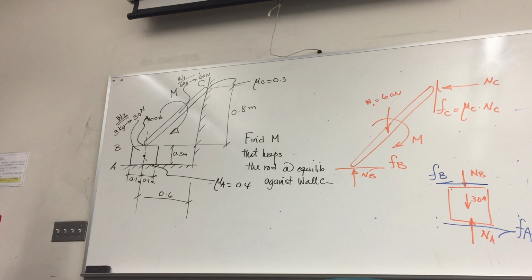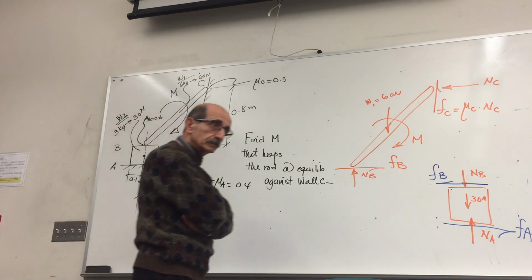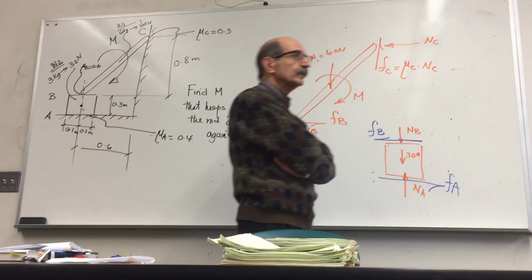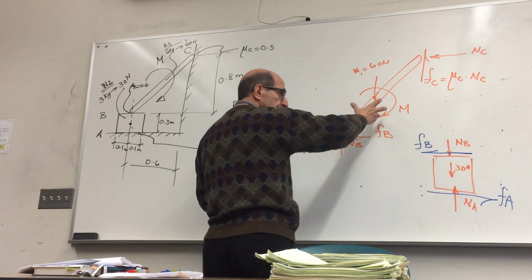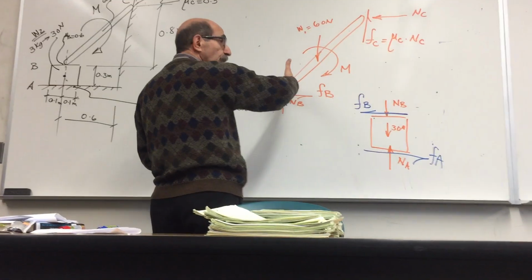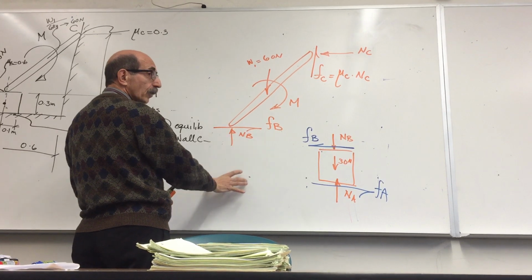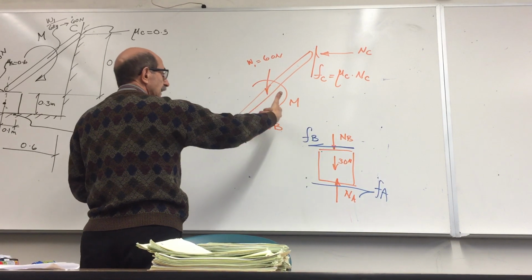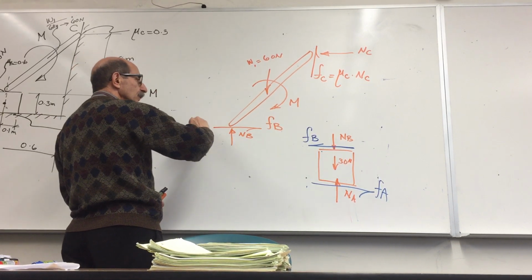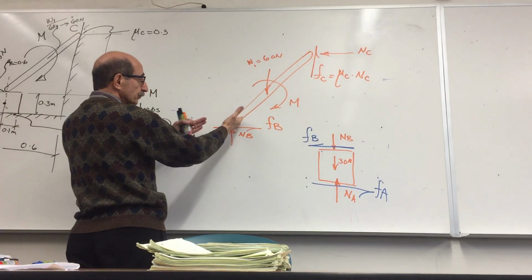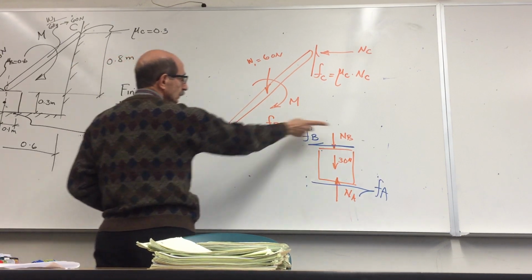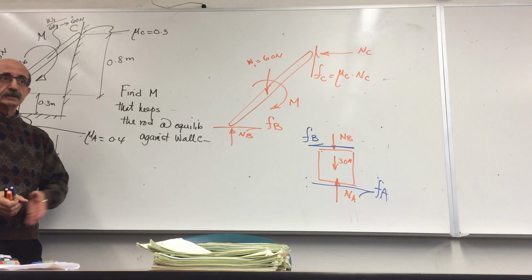Yes? Doesn't friction come from a reaction, like there's no friction resisting movement in this direction until I move my phone, right? Right, that's right. And that's what is happening here. Because when you apply this, it is trying to move this bar with respect to the box. So since this is going to move with respect to the box this way, that means along the surface of contact, since the bar is moving in this direction, the friction force that is resisting its motion would be opposite to the direction of motion, right?